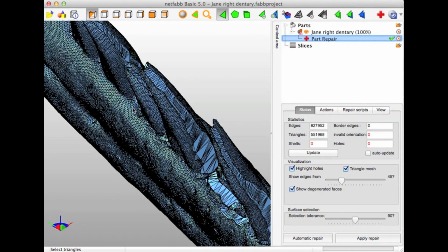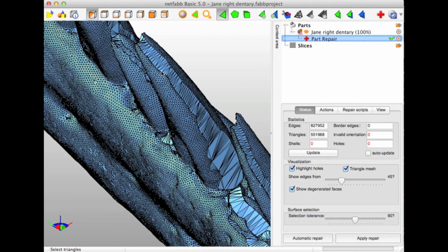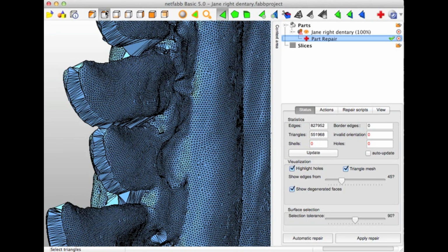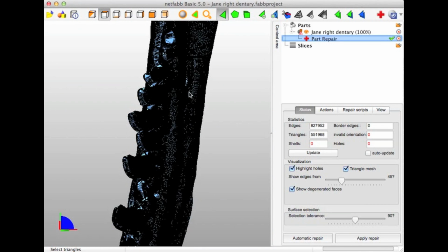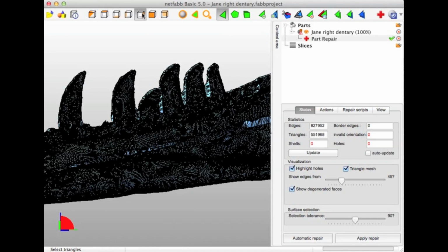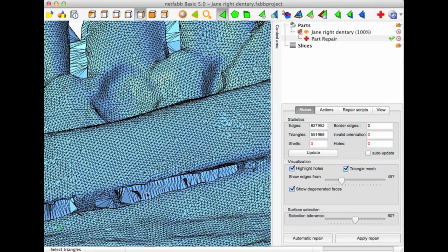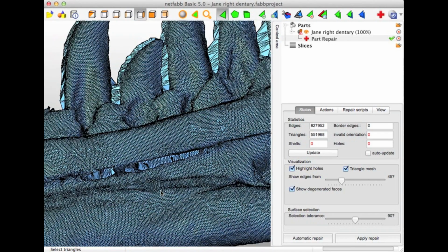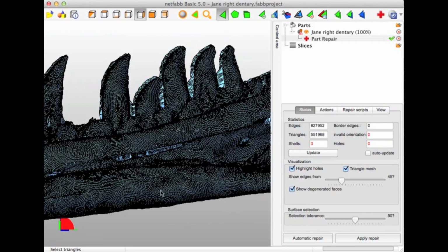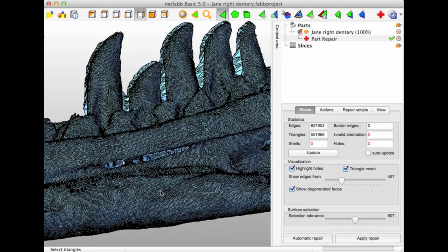And you can see, as I approach the point cloud, that it's now stitched the open areas, and it's turned that into a solid mesh. Then we'll look at it from another angle, and I'm just checking to make sure it did not place vectors anywhere where I would not like to see them. It's actually done that in a few places. You can see right where I'm dragging my mouse, it's added vectors to the open space, but I am not going to worry about that in this case because it is a minor error.